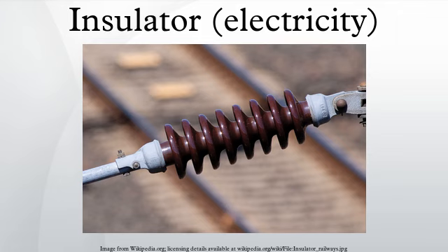History: the first electrical systems to make use of insulators were telegraph lines. Direct attachment of wires to wooden poles was found to give very poor results, especially during damp weather. The first glass insulators used in large quantities had an unthreaded pinhole. These pieces of glass were positioned on a tapered wooden pin, vertically extending upwards from the pole's cross-arm. Natural contraction and expansion of the wires tied to these threadless insulators resulted in insulators unseating from their pins, requiring manual reseating.